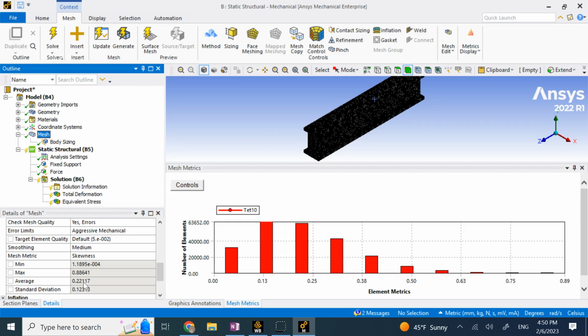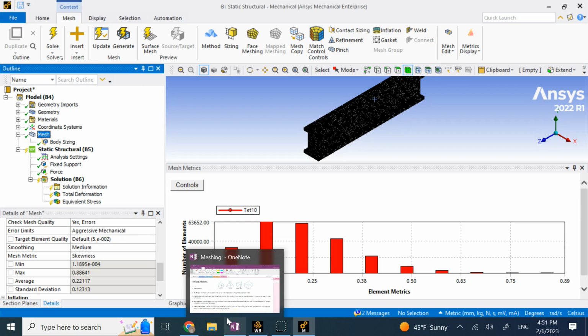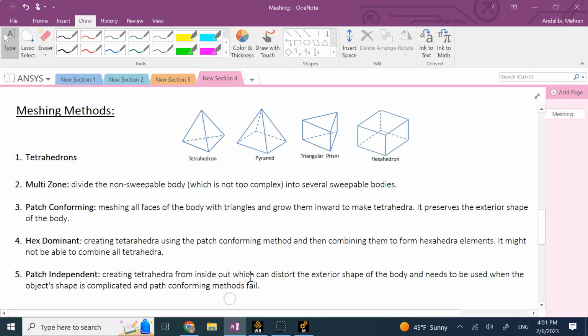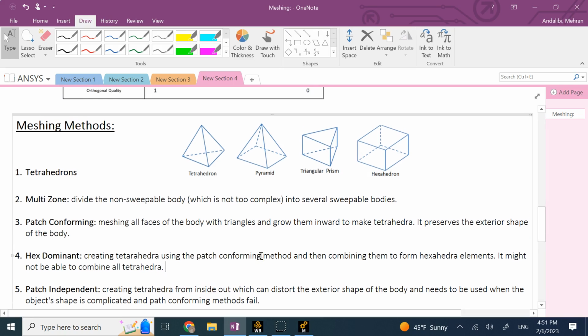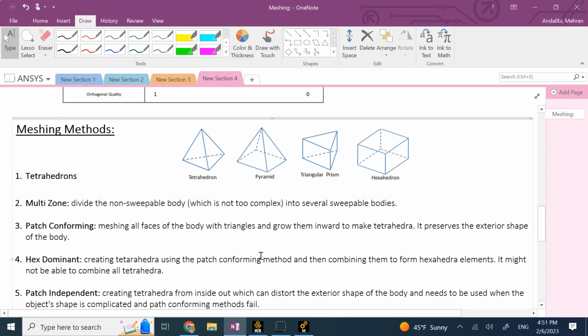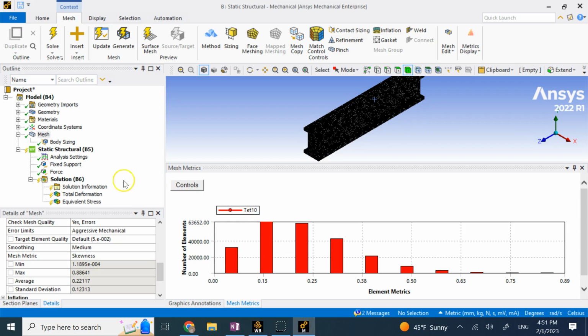And your collection of finite elements is now very close to the actual geometry, so your calculations should be relatively good. So just keep in mind, as I mentioned, that just going down on the size is not necessarily always a good thing. It means a lot more computation. Sometimes it means the stress singularities that you have to avoid and skip. And you have to know when to stop reducing the size. And I showed you the convergence method, and I showed you a mesh quality metric to kind of guess when we should not go any further down.